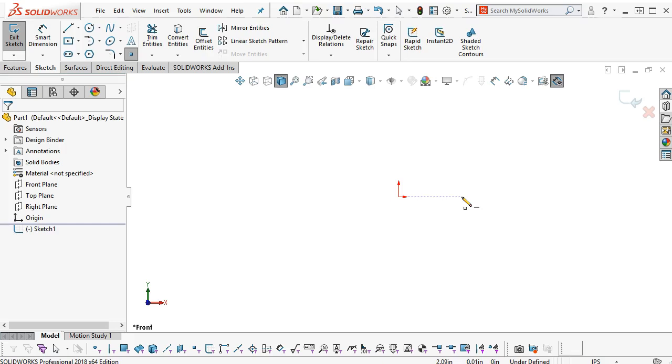Looking at the two icons, the pencil is showing me that I am sketching, the lower left icon is showing me that I'm generating a point, and the right icon in white background is showing me that it is horizontal to the origin. When this comes up and goes vertical, now I'm seeing a vertical with a white background, and that indicates that while it may be vertical, I'm not going to get the inferred relation of vertical between those points.